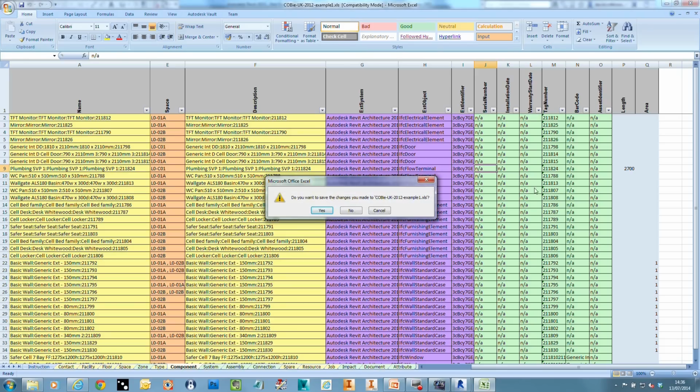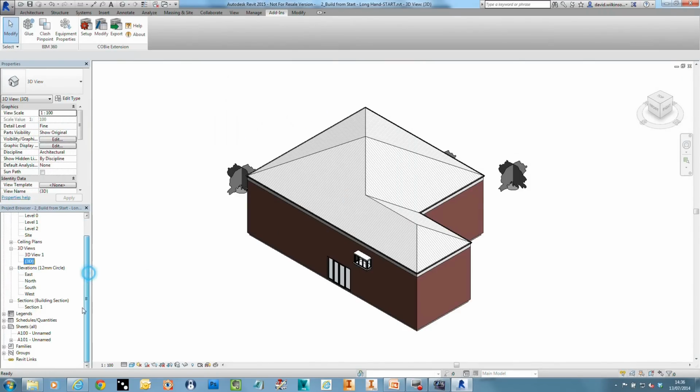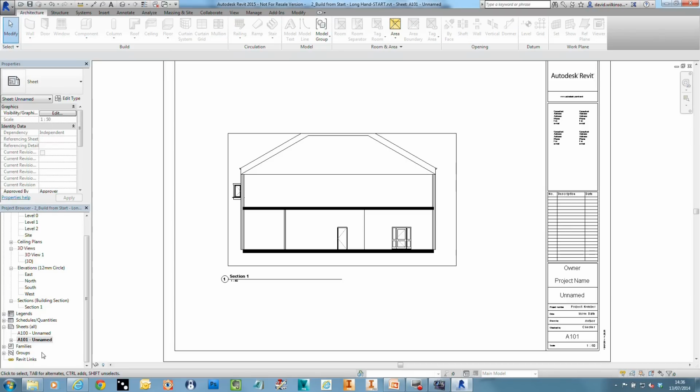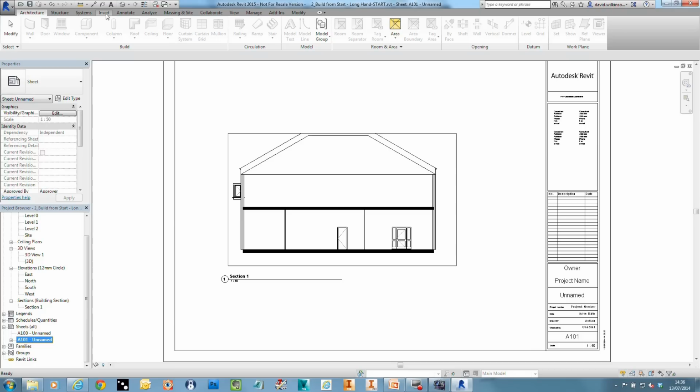So, hopefully, oh, just one other thing as well, I'm not going to do it, but just quickly talk about it. Obviously, most people that are coming to Revit, new, if you like, or being introduced to Revit, would be coming from an AutoCAD background. So within our drawing sheet, we can export these out. We have options where we can save them out to an AutoCAD format, as you'd expect. If your delivery format's AutoCAD, then you can do that as a standard DWG file. You can link that back as well.